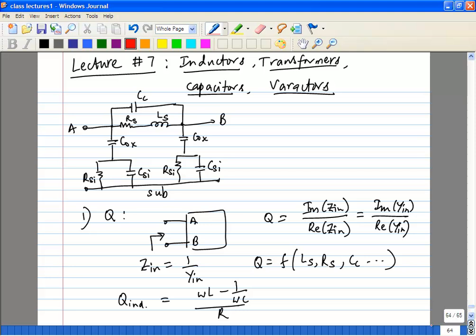Exactly, you can't say whether Q improves without analyzing what the distances are, without really running the electromagnetic tool, okay? It is not that intuitive. It depends on the actual distances from the substrate as well as the actual resistivities of your metal lines. Is that clear?